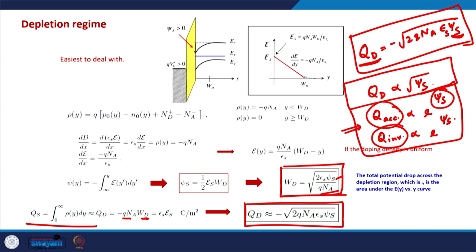The depletion charge we have calculated precisely, and I would like you to think more about how we are saying that the accumulation charge and the inversion charge are exponentially correlated to the surface potential. Please go back to the basics of the carrier statistics in semiconductors and see it there. You would find it will be a pretty much straightforward relationship.